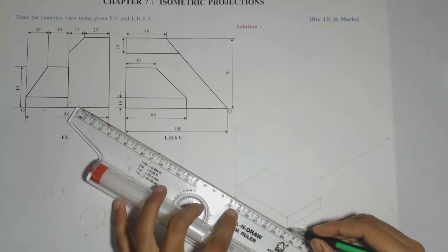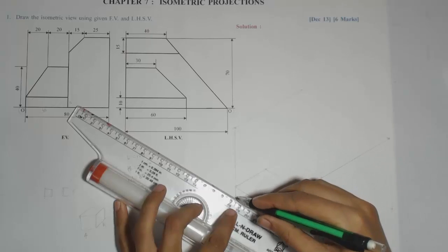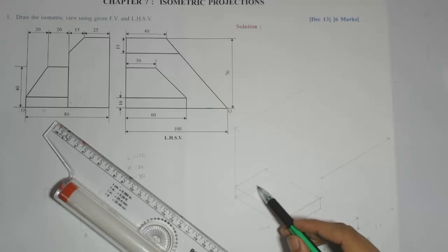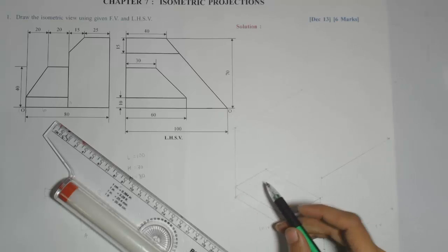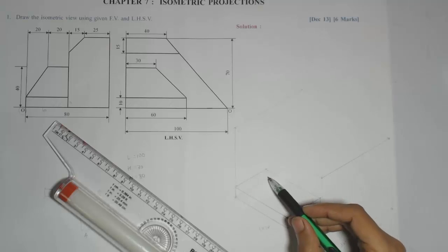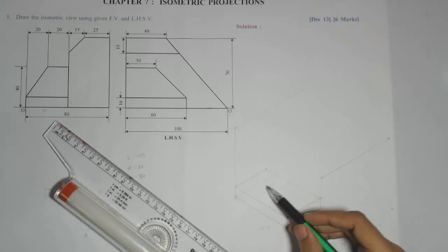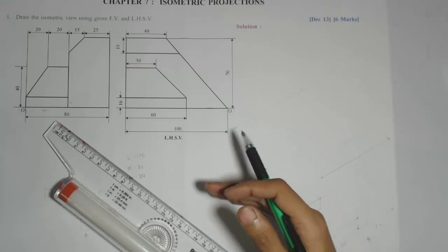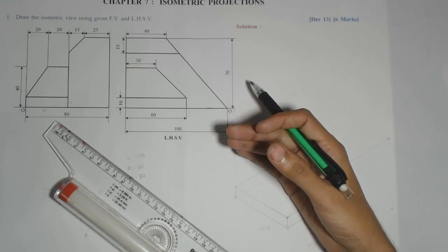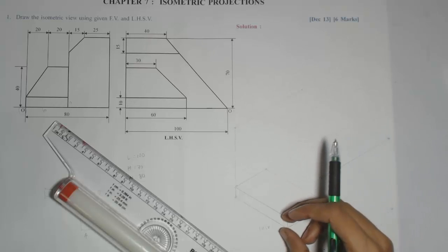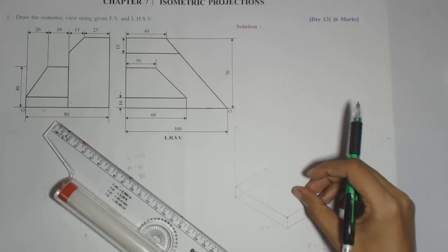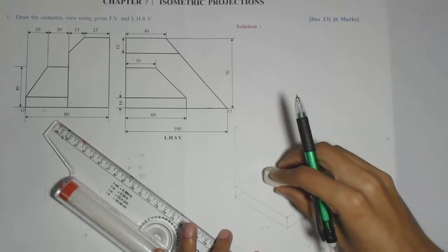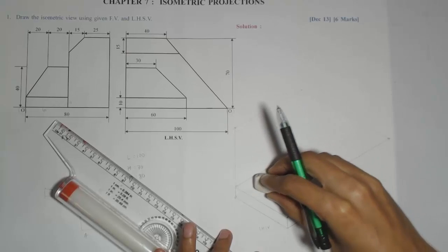Okay, now if you see, I have marked only some lines dark, because if you see, projector from this corner, observer is not going to see this part, because this line is not visible to the observer, because this plane will be visible first, and whatever is behind that plane is not visible to the observer. Similarly, this plane will be visible, and obviously line passing through this will not be visible. So I'll erase those lines, because those are not visible to the observer.